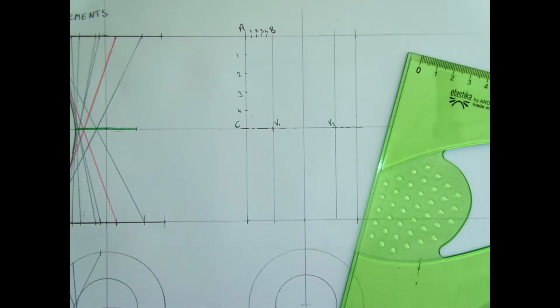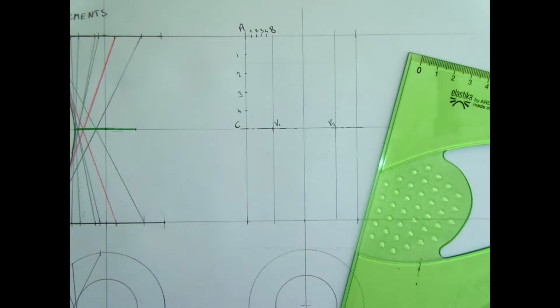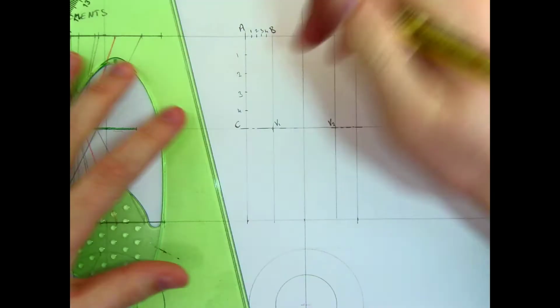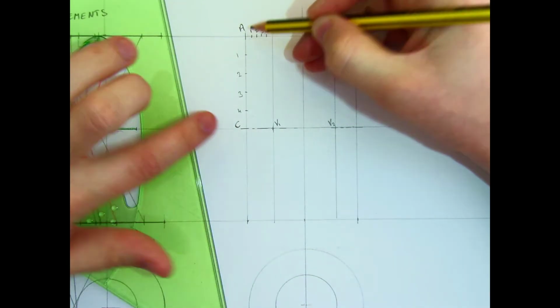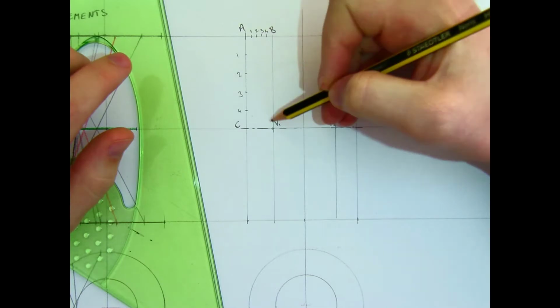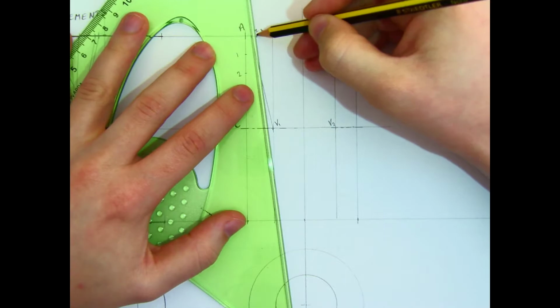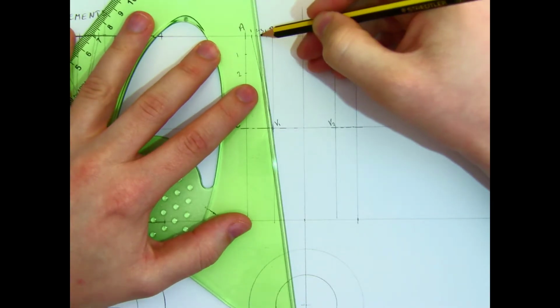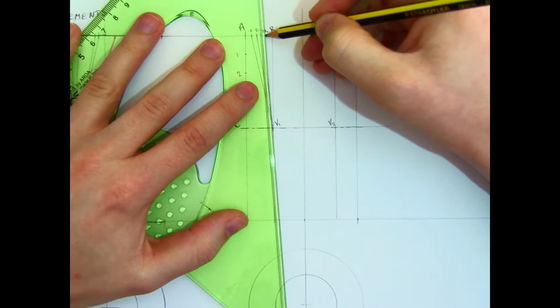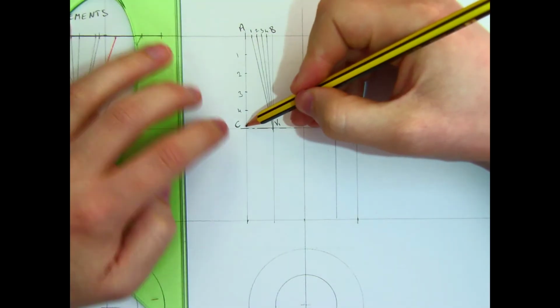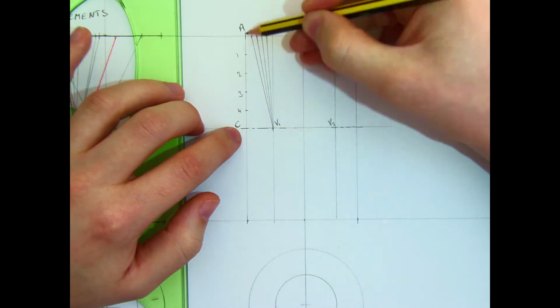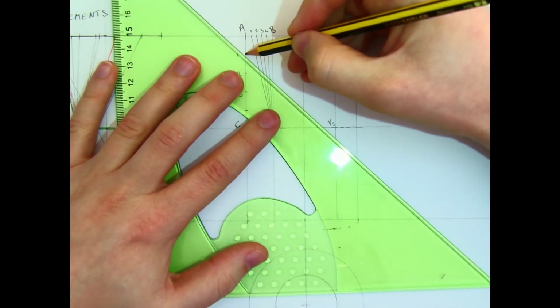Now, what we need to do is join our lines to the different vertices. So the points on the line AB, the lines which are parallel to the axis, are going to join to the near vertex. So these ones here, they're parallel to my axis, which is this one, so they're going to join to the closer vertex. So these join down along this way, all light lines. The ones that are perpendicular to the axis along the line AC, they join to the far away vertex.